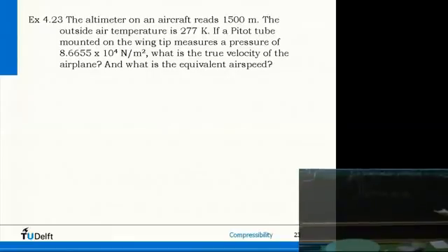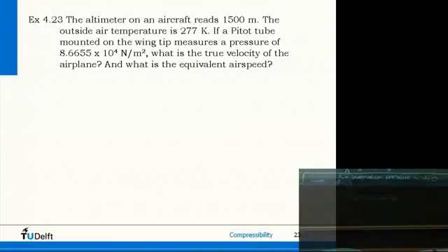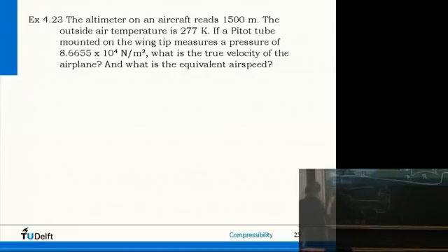We also have pitot static tubes, and that is connecting this one to another with typically a manometer. So suppose you have a channel, you connect this, again, differential pressure gauge now, to this tube. In this way you can measure differences, right? So here you can measure total pressure, and then here static pressure. Why does it measure static pressure here?